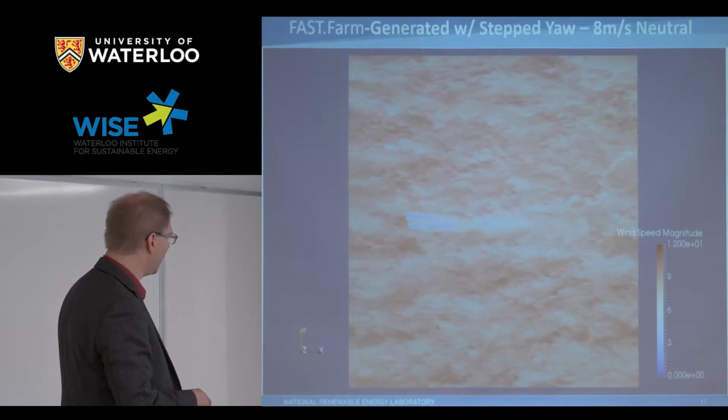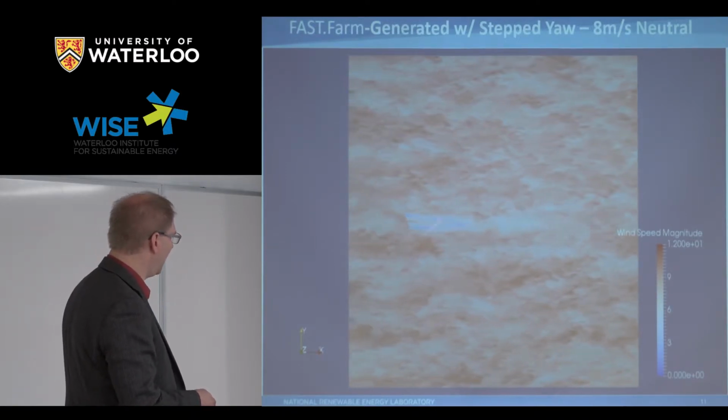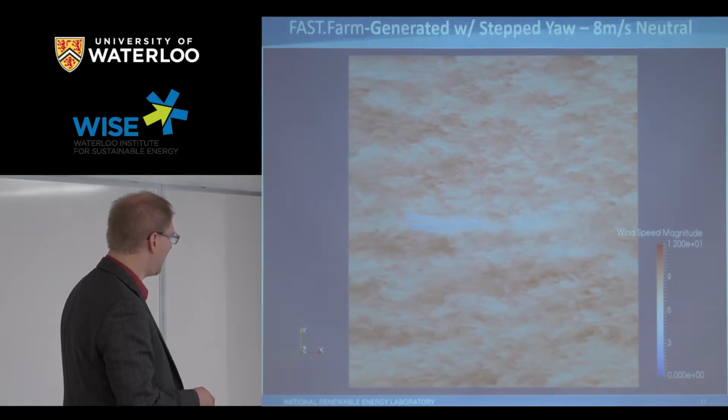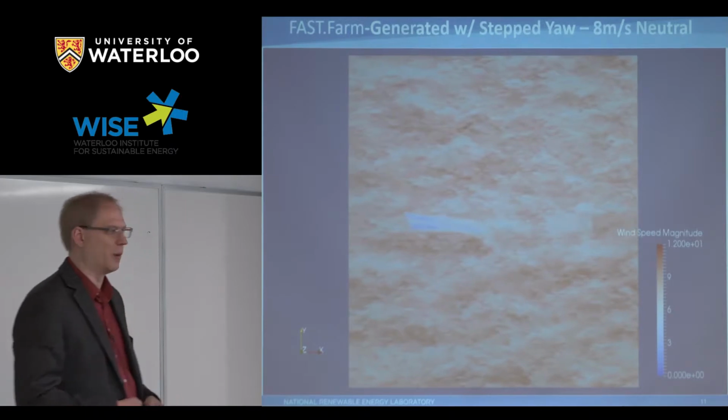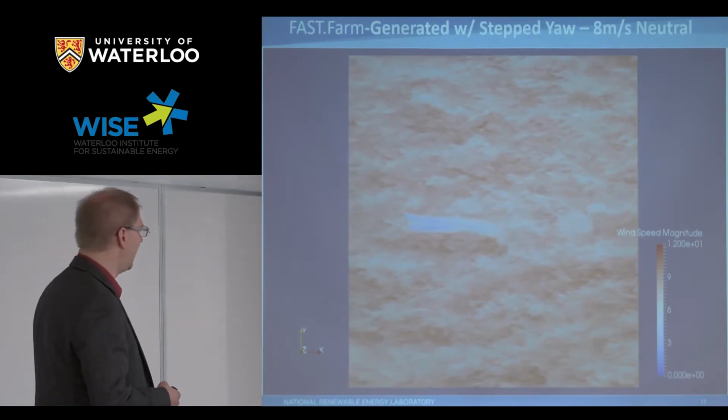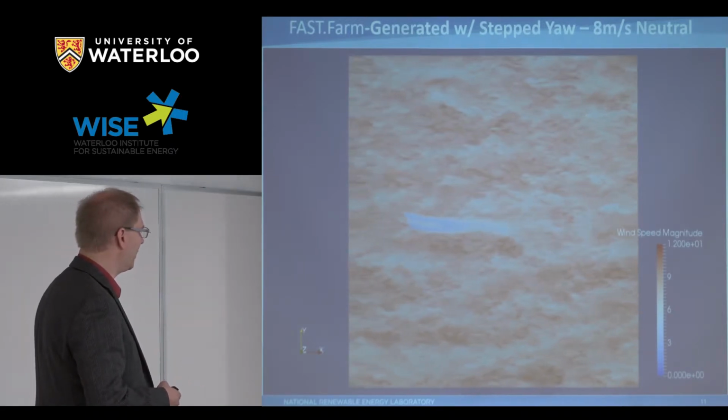What I did there is I simply yawed the turbine now. Basically yawed at 10 degrees, and I think I yawed at 25, and you clearly see the deflection of the wake starting to form from that. So we capture those effects within the formulation.